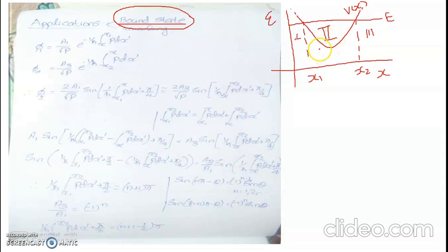And in this region, we know that if you disturb the system that is occupying, say, a position coordinate somewhere here, any kind of disturbance will impart a restoring force upon the system, and the system will have a tendency to return to its equilibrium position. As a consequence of the inertia, it will overshoot the equilibrium position and go to the other side. This accounts for an oscillatory motion for the system in region 2.